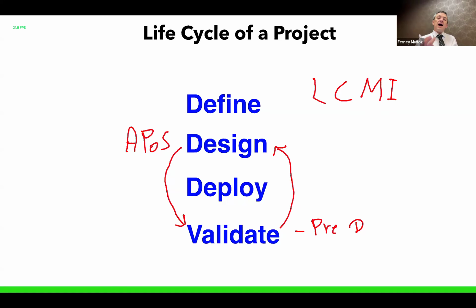So if you can do a pre-deployment validation, going on site, and it's not just measuring the heat map and how far the waves go from that AP, it's measuring the attenuation of walls, pillars, obstacles, heights, distances. It's looking at the entire construction site and getting things on the floor map documented. I get floor plans sometimes that say, yeah, that's going to be a glass window over there. And then I go on site and there was the glass. Like, oh, no, they changed the design. This is going to be brick now. And then you're going to have to modify your design.